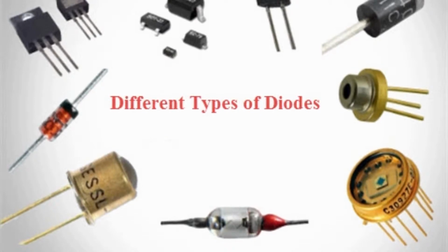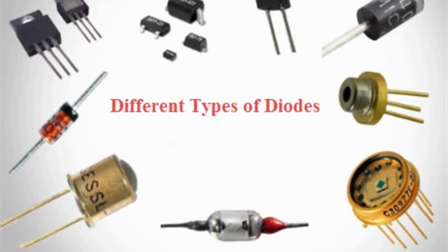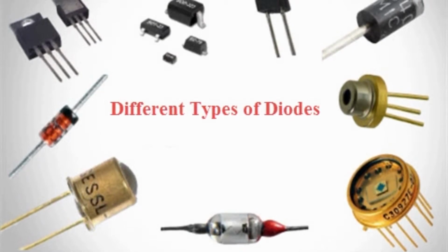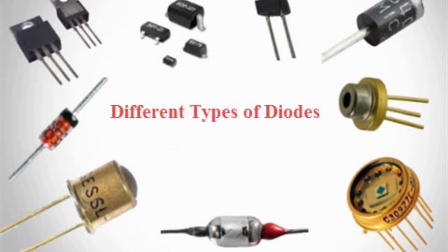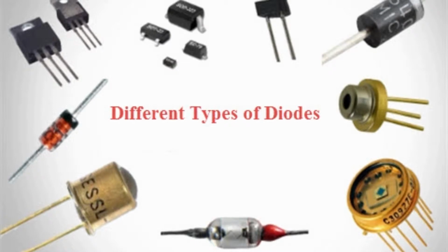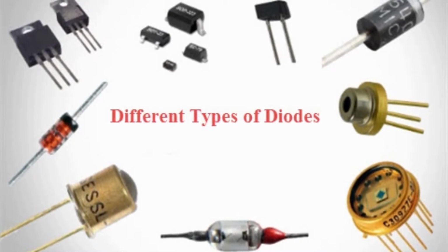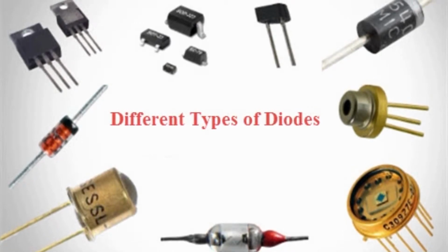The characteristics of a diode closely match those of a switch. An ideal switch when open does not conduct current in either direction, and in the closed state conducts in both directions. Ideally, in one direction, that is indicated by the arrowhead, the diode must behave as a short circuit, and in the direction opposite to that of the arrowhead it must be an open circuit.